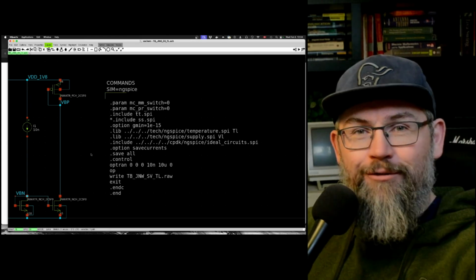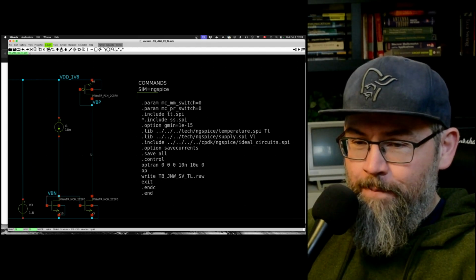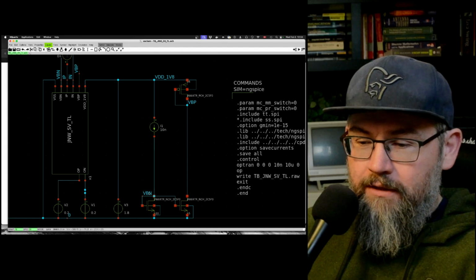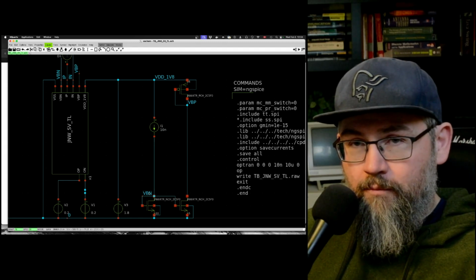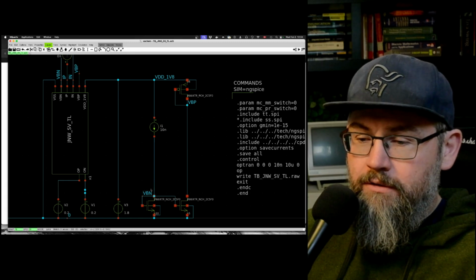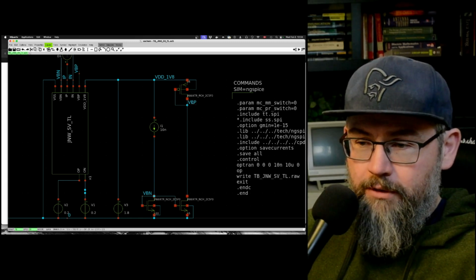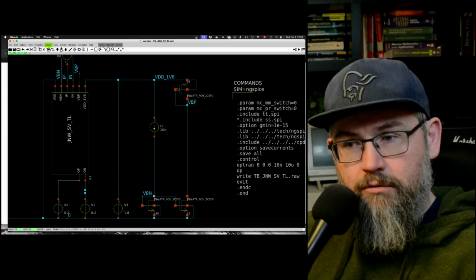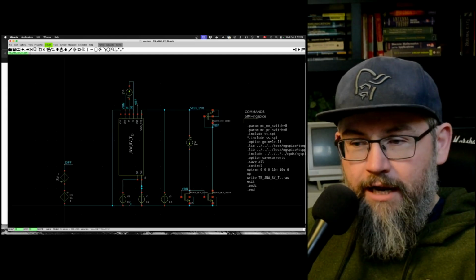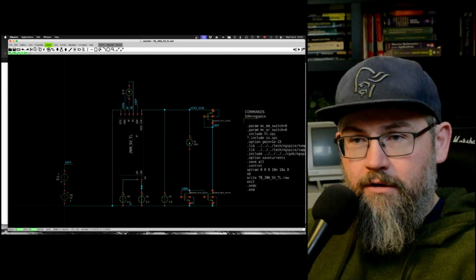If you don't, then go have a look at some of my tutorials. And then we have some bias. We need a bias voltage for the NMOS current mirrors, and we need a bias voltage for the PMOS current mirrors.